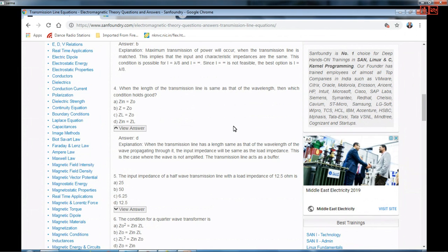Okay. Similarly, we also need this sort of transmission line for our radar operations, where the radar has to identify only a moving target. That means the previous return signal from the target and the present return signal from the target, we try to compare and see whether there is any difference between them. Then only we are going to give an indication.